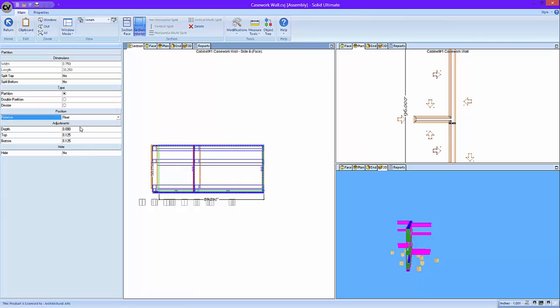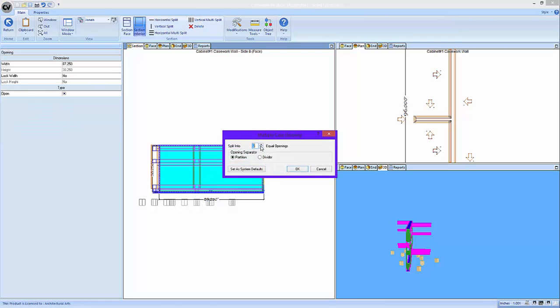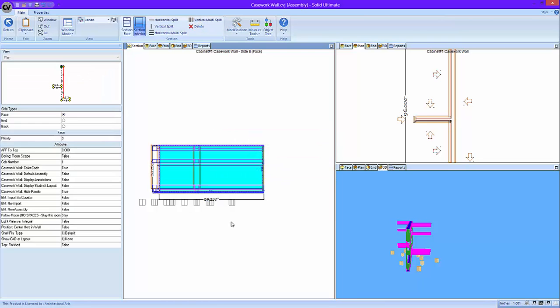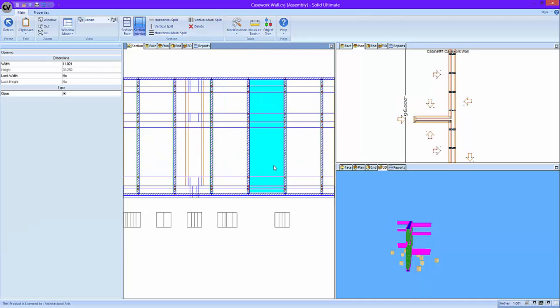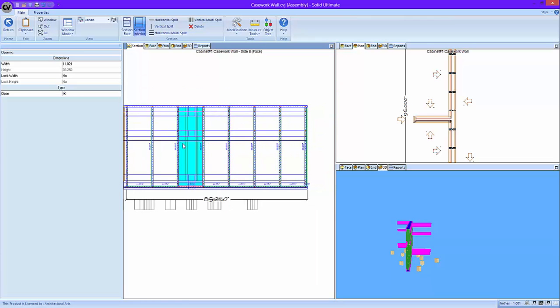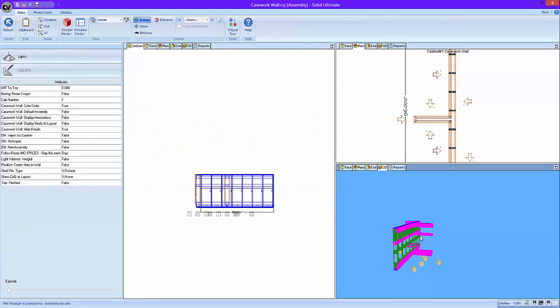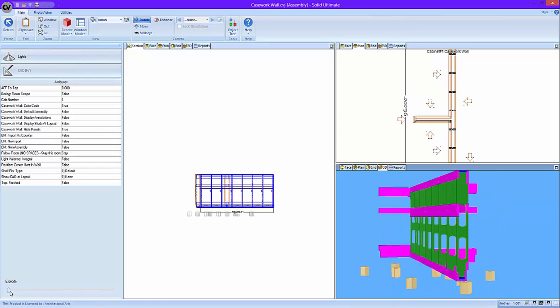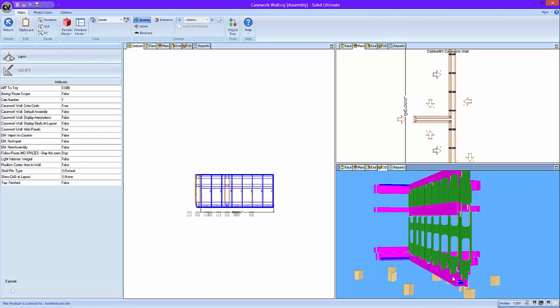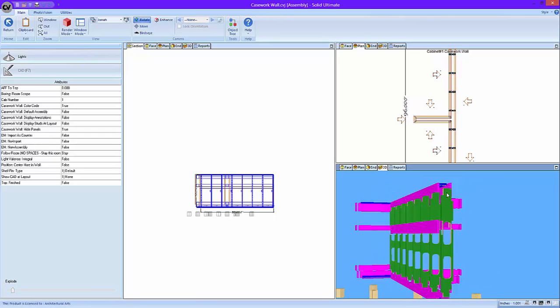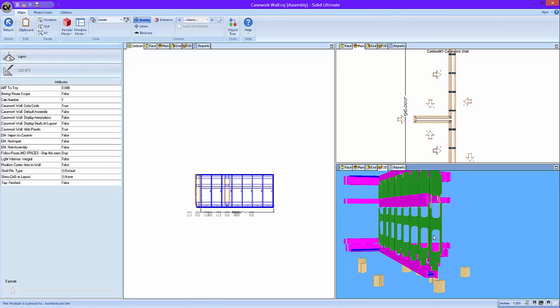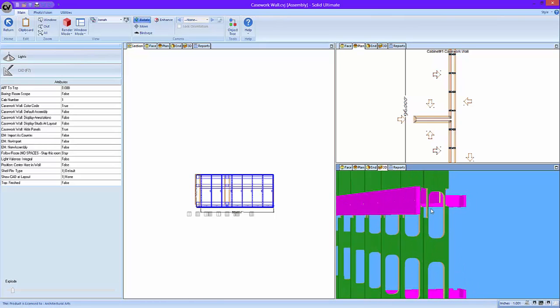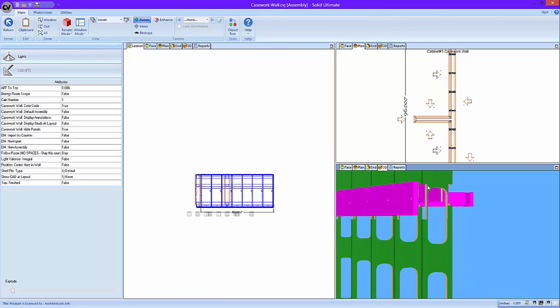And over here, we're just going to send it all the way to the left. And then we're going to split this up into, say, 7 openings. I don't mind that. I usually aim for 12 to 16 inches between studs. And you can see, if we explode this, we're getting a notch for each cleat. And we're getting these wire chases cut in, which we'll want to come back and adjust because there's like 1/8 inch of material there.